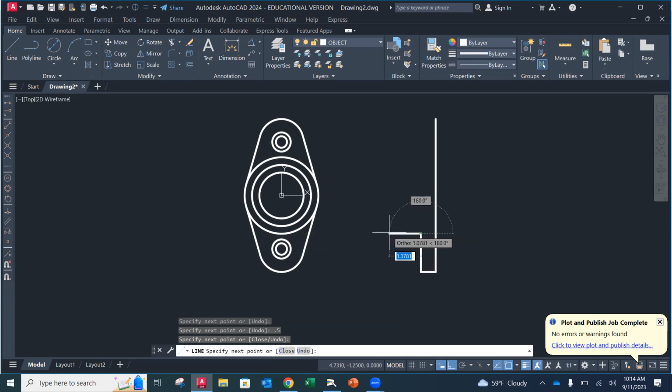And then I have to look at how high that is. So this overall is 2 from the top to the bottom. I used a 1/2 inch already. So that means I'm going to be 1.5 in this direction. Then I'm going to go straight up. I'm going to find that outside. There it is for me this time. And then this one, depth-wise, I could do the 1.5, or I can hover over this one, go straight up. There it is. And then go up, hover over. And because this is a continuous line, I can do C, enter, and it closes for me.